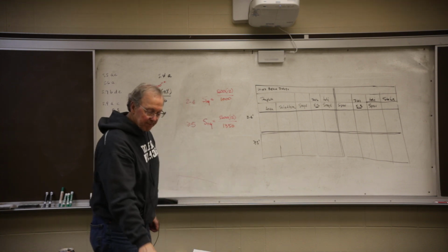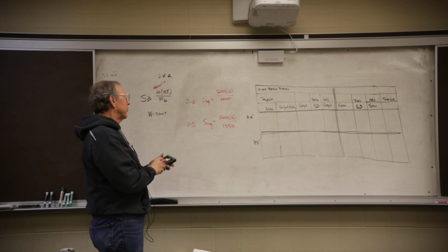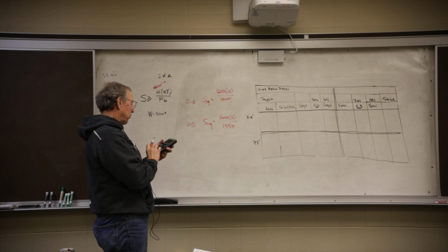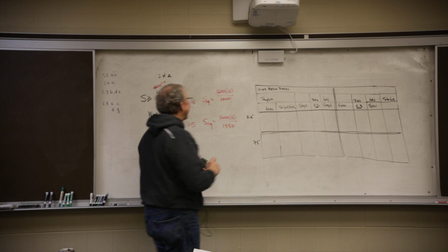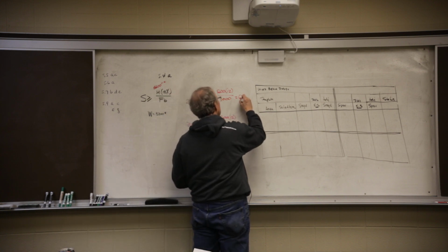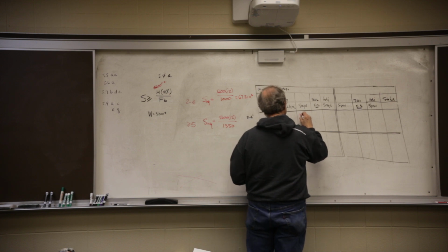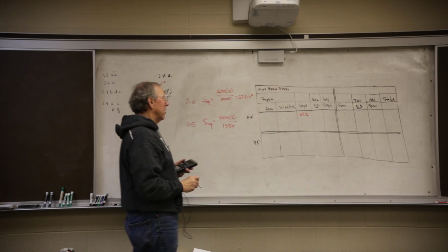Do the math. I think you got the section modulus required for each of the two. So I'm going to put 5,600 times 12 divided by 1,000. And I get 67.2 inches cubed. That goes right here. So that's the first column you're going to fill.